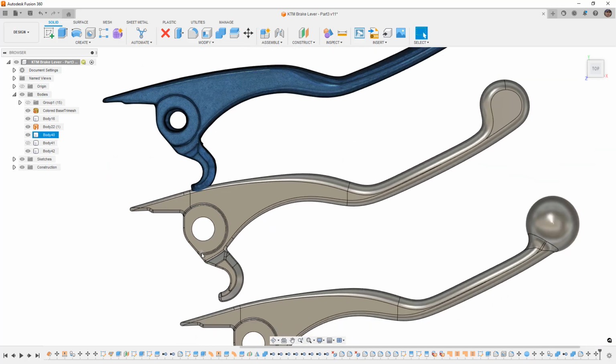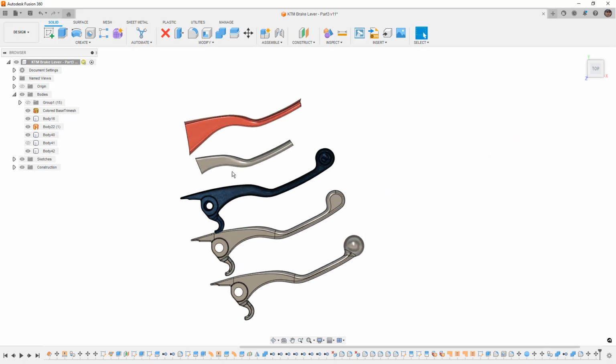So at this point, I don't have any intention to try to replicate what we did here with the mesh section sketch or the freeform body. Again, because in this instance, I don't feel like those are the best options. I think that reverse engineering the part with the design intent and using prismatic features is the best way to go.